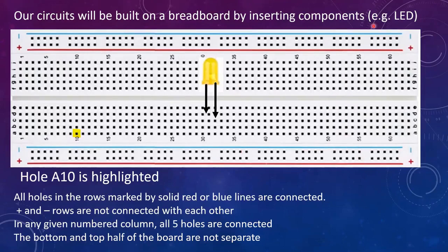The two sides look like mirror images because they are, so the whole bottom and the whole top are just mirror images to each other. They're not connected. It's basically like you have two halves that are just repeats of the same thing. If you want to have a component on this side that gets power from this side, you actually need to send a whole wire down. Nothing is connected underneath between the bottom and the top half here.